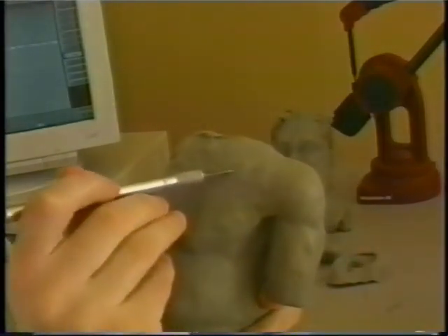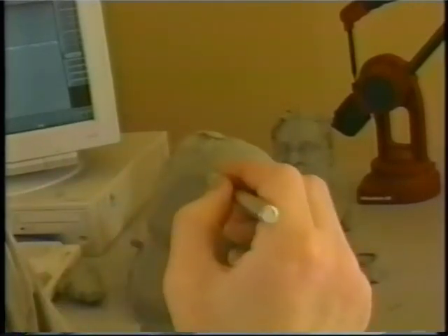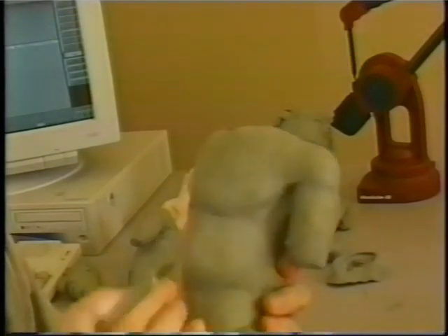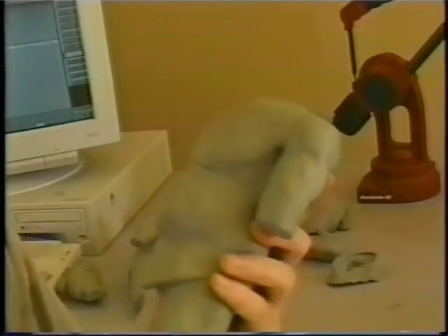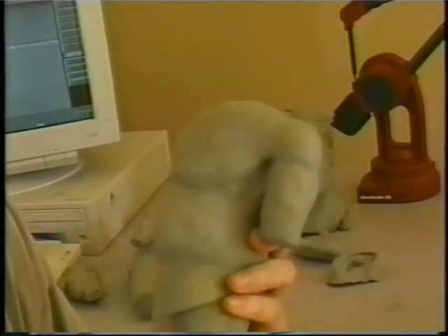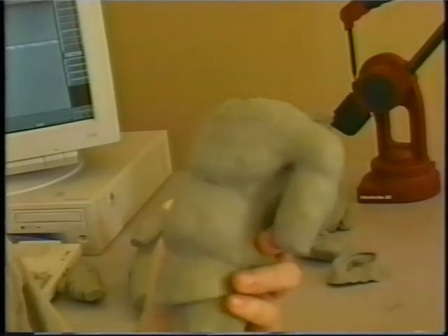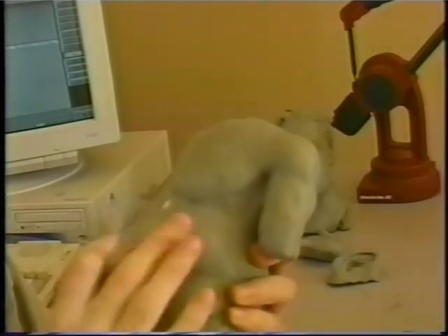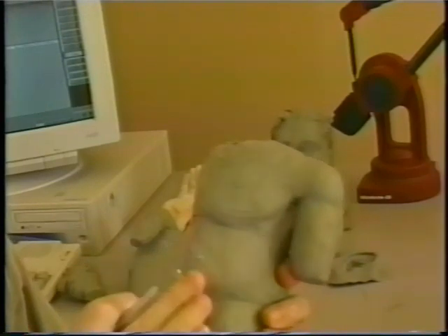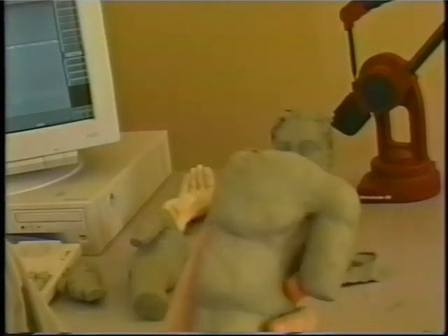So for instance, here's a collarbone. Do you want to put one line and make it very simple, or do you want to put two at opposite ends of the crest? And again, the more you get to know NURBS or B-splines, whatever patch format you're using, and how it will flow, the better you'll be able to mark things up for digitizing.